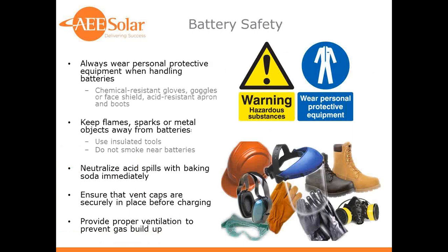Battery safety, very important. You're dealing with sulfuric acid solution in the battery. It's very corrosive. It's very damaging to skin and eyes if you get it on you, and very damaging to clothes if you get it on your clothing. I would warn you, if you're dealing with lead-acid batteries, to never wear a nice pair of blue jeans.